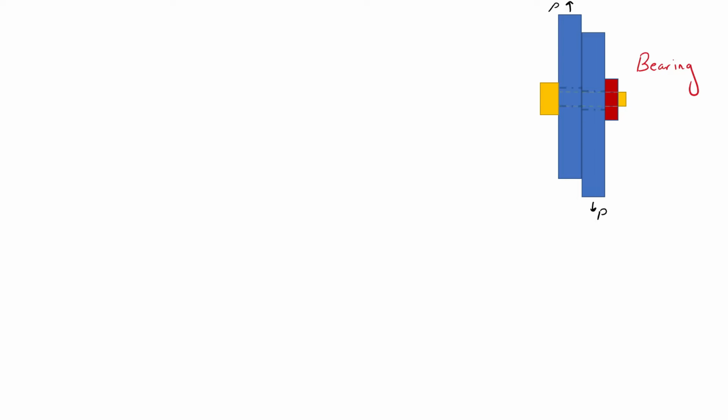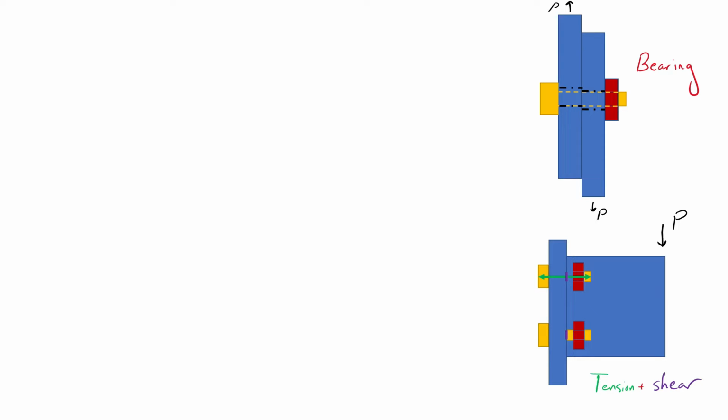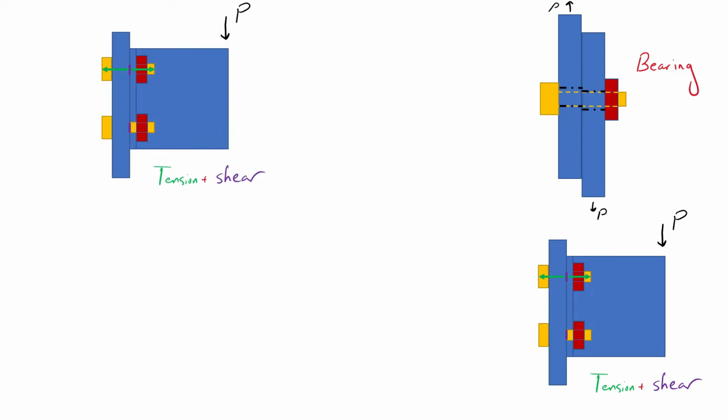Not all high-strength bolts need to be tightened to the fully tensioned condition. Snug tight installation is allowed for bearing type connections, where the bolt shank is allowed to press against the connected parts. Snug tight installation is also allowed for tension or combined tension and shear applications, unless the connection is subjected to cyclic loading and fatigue is a concern. Then pretension bolts are required. Pretension bolts are also required in dynamic applications or in the presence of vibrations where bolt loosening is a consideration.